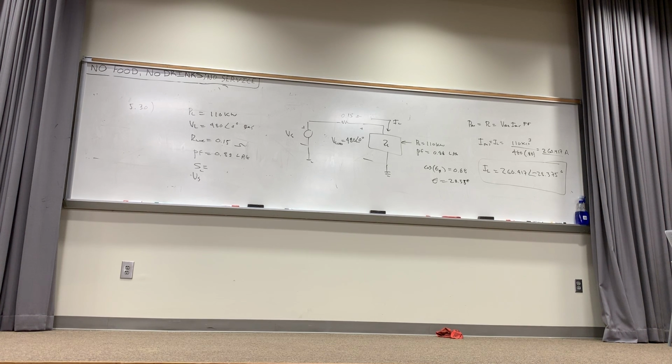Remember, everything we deal with is the current's relative phase with respect to the voltage. The voltage is almost always the load voltage at 0 degrees. If it's lagging, the current is behind that angle, and if it's leading, the current would have a positive angle. When I say something's leading or lagging, think about plotting two waveforms on an oscilloscope. If there was no phase difference, they would be identical except for the magnitude.